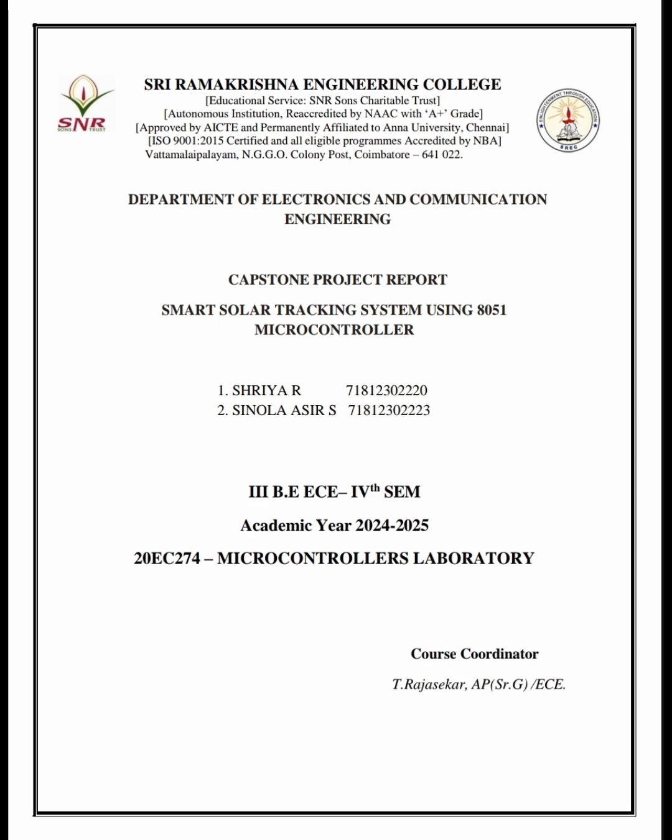We used an 8051 microcontroller, LDRs to detect sunlight, and an ADC to convert analog light signals, a DC motor to rotate the panel, and an LCD to display intensity. The logic is simple. Based on light intensity, the solar panel rotates left, right, or stays still.